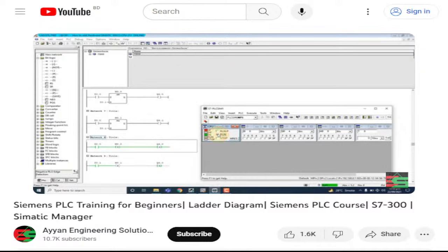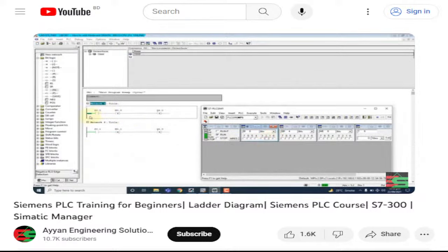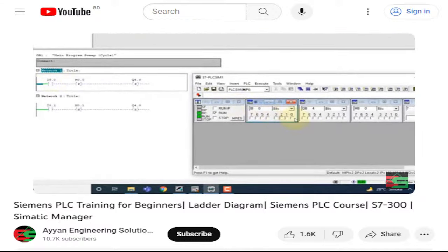Now the PLC is on, and you can see this time both inputs are off, so no start. When I turn on the input I 0.0, your output is set because this is a positive edge. Now I want to reset this coil, so this is a negative edge. When I move this input from 1 to 0, then your coil will be reset.